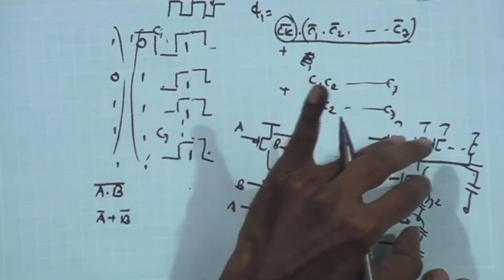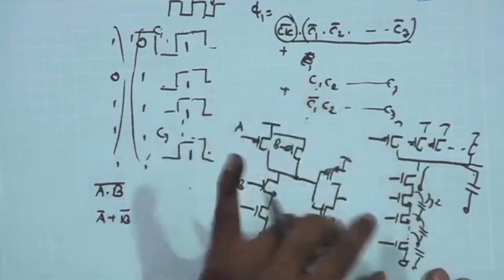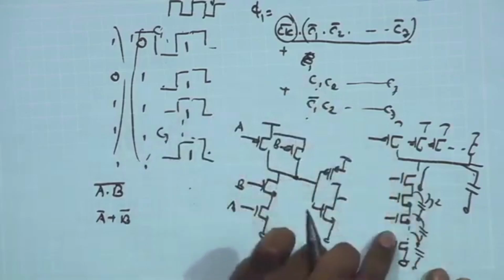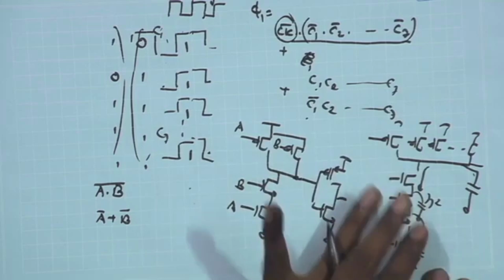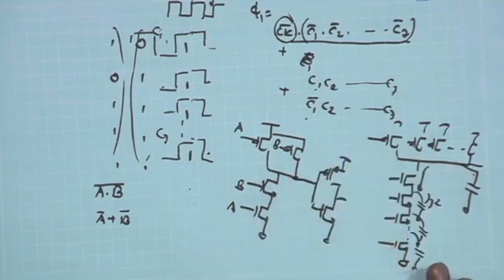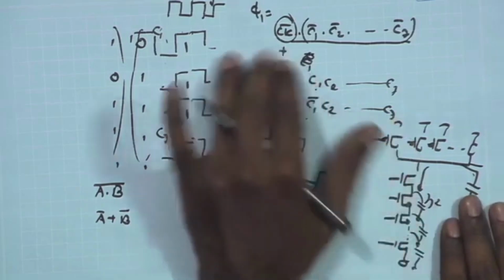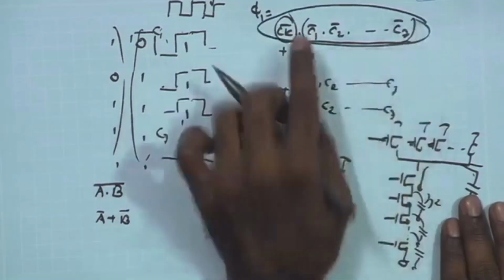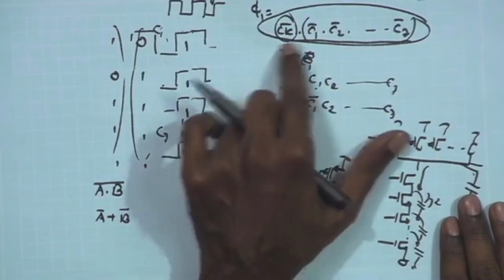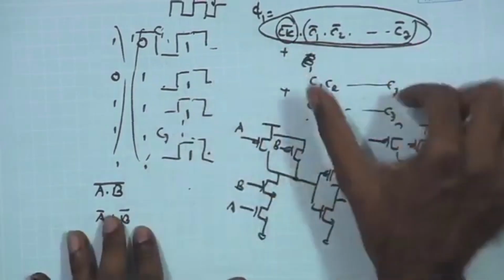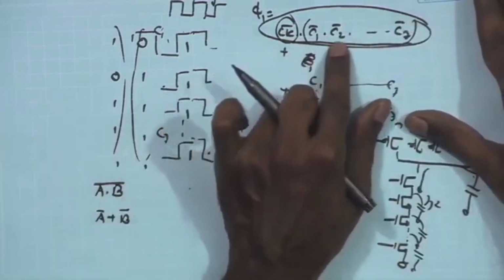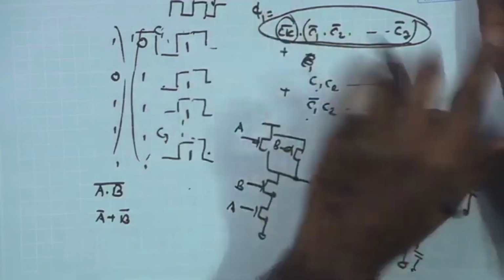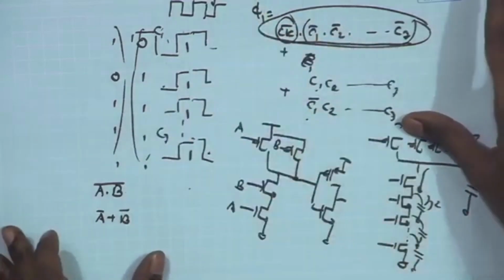Therefore, generally people do not go beyond 4 input. So, the maximum number of inputs that you can see in standard cell libraries is 4 input, better is maybe 3 inputs and so on. Beyond 4 input it can degrade the delay pretty significantly. So, in our case, since we are having say 7 or 8 inputs, in our original case we started with this particular combination CK bar, C1, C2, C3, C7. So, we can split it into 2 halves, 4 and 4, and then implement the CK bar, C1 bar, C2 bar up to C3 bar, and then another one, and then AND them together. That can be one solution.